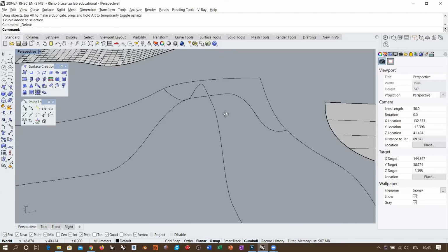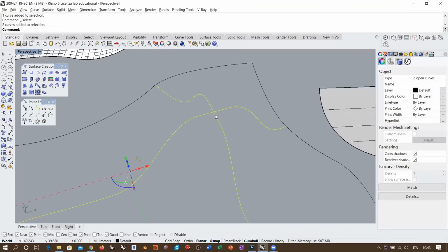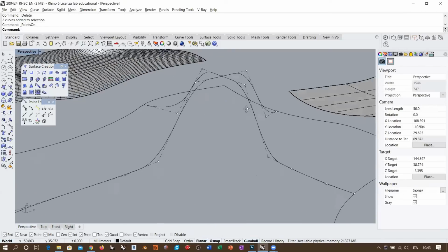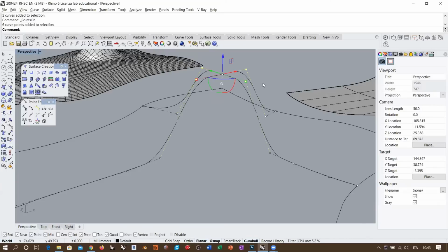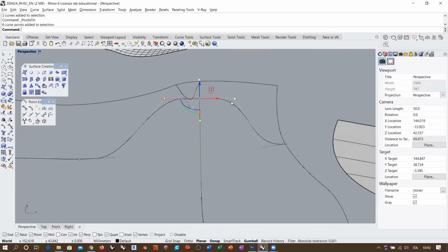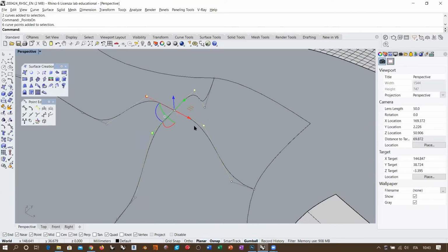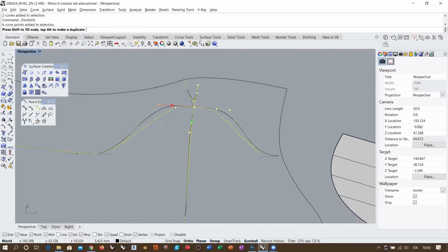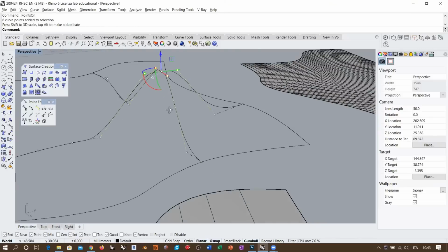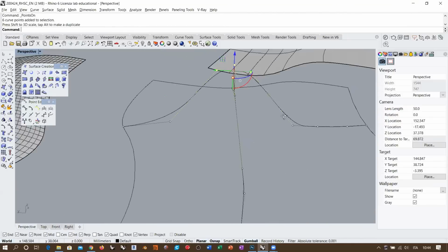And as we have access to the topology, we can activate the control points. We have this cross of points here, which we don't need the diagonal of, let's say, because this is not a surface. It's not a two-dimensional domain. These are two one-dimensional domains, okay? So I only need 3 points and 3 points. And I can decide this bulge, how rounded or how smooth or how squarish it is, okay?